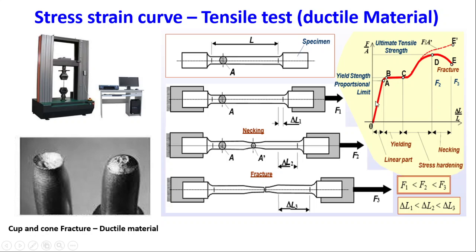Up to the yield point, it is observed that the stress and the strain are proportional to each other, and beyond the yield point, the material converts from the elastic to the plastic region. With further increase beyond this yield point, it is observed that the strain rate is increased, and further addition of the load forms a neck.